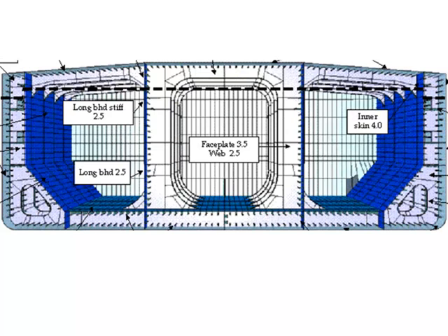Our goal is to analyze the ship hull to all possible failure modes, to all load cases, to ensure required safety for each, and to optimize, size concurrently, all of the plate thicknesses, frame and stiffener heights, spacings, and cross-sectional shape dimensions in order to achieve the lightest weight and most efficient structure.